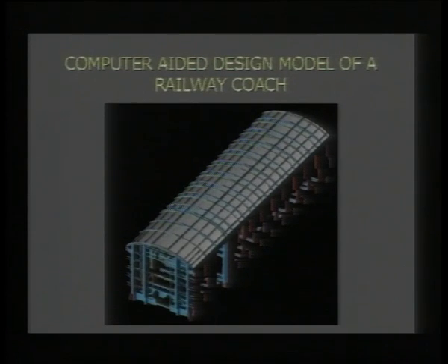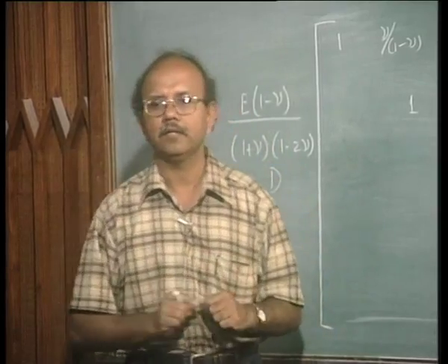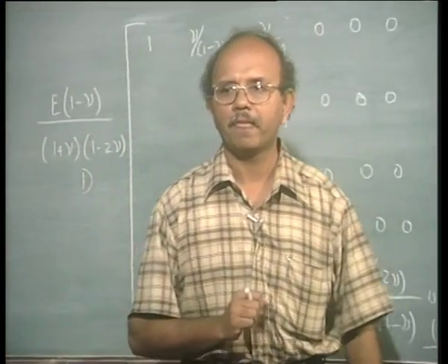What is the type of element that you will use? Plate, okay. So I have heard the terms plate, shell, and so on. Let us now discuss this beam, plate, and shell, and complete our vocabulary to a certain extent on the type of the elements that are seen.